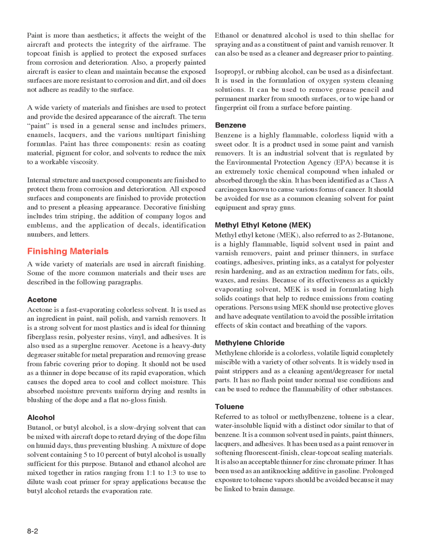Benzene. Benzene is a highly flammable, colorless liquid with a sweet odor. It is a product used in some paint and varnish removers. It is an industrial solvent that is regulated by the Environmental Protection Agency, EPA, because it is an extremely toxic chemical compound when inhaled or absorbed through the skin. It has been identified as a Class A carcinogen known to cause various forms of cancer. It should be avoided for use as a common cleaning solvent for paint equipment and spray guns.